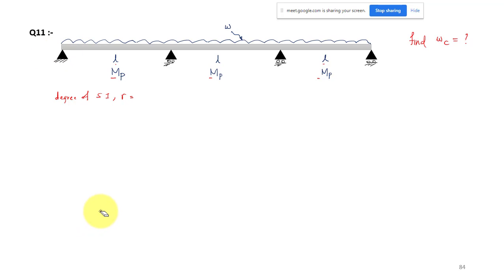If I count two here, 1, 2, then 3, 4, 5, so 5 minus 3. You can also do it this way because the loading is only vertical, so the horizontal reaction I can eliminate. Finally, I will have 1, 2, only vertical 3 and 4, so 4 minus, and I have eliminated one equilibrium equation also, 4 minus 2. So with both methods you get the indeterminacy as 2.